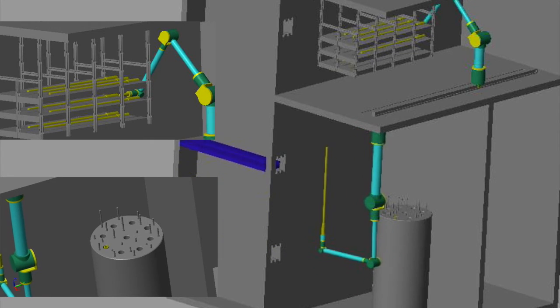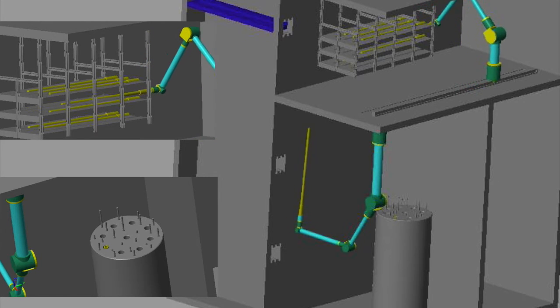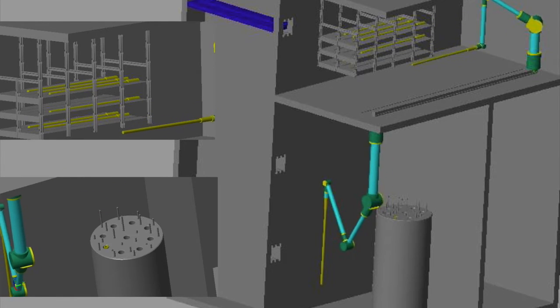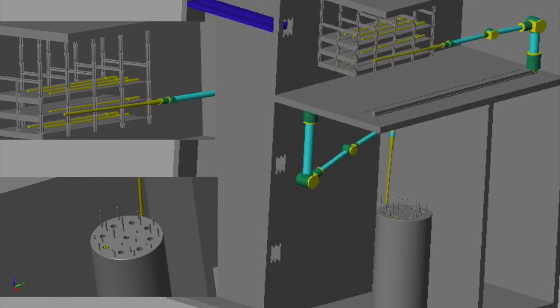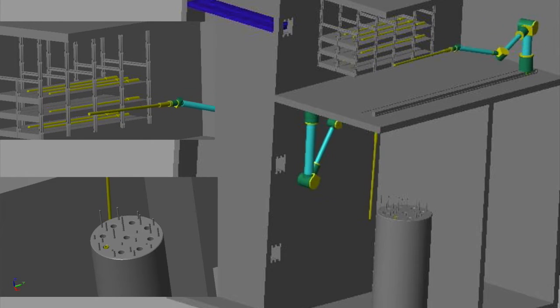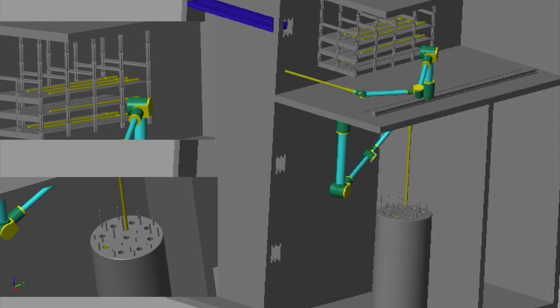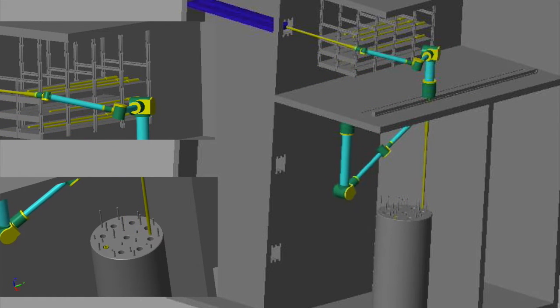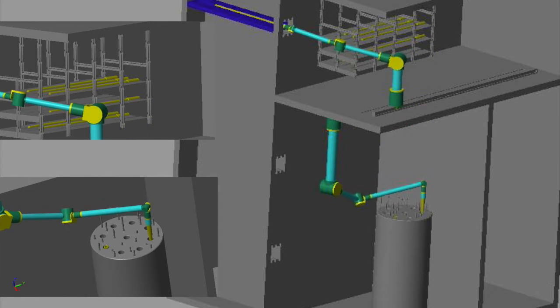The function ikunc is very similar to ikine, but no mask input is passed, and optimization techniques are utilized to calculate the inverse kinematics. jtraj generates the time-dependent trajectories between the start and end joint configurations. Default 0 velocity and accelerations are used at the boundaries. The output of jtraj is joint angles, joint velocities, and joint accelerations along the path.